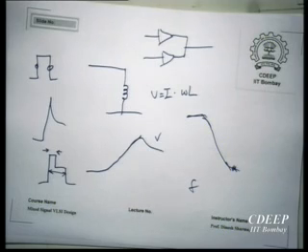So essentially for high speed drives where you don't mind spending a little more power, it is better to have an overdrive circuit at the transmitter end. When power is everything and still you want to have as high a speed as possible, then it is better to have inductive termination, and that means our beta multiplier is still not dead. You still want to use it. And if it is slow, then of course it doesn't matter because then the current comparator is not such a big limitation. So that is the overall resolution, which is where we are right now.